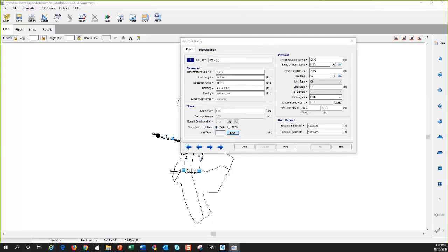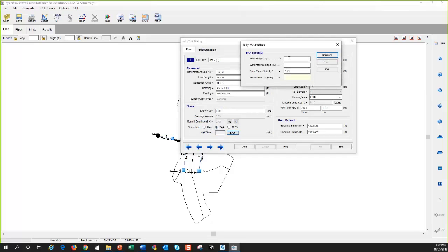I pull that up, and again, I took some measurements in Civil 3D, and in this drainage area I've got 277.19 and a slope of 0.22. We've got the weighted runoff coefficient, which was calculated up here. Now I'm going to compute the time of concentration. Everything is populated here, and I exit.